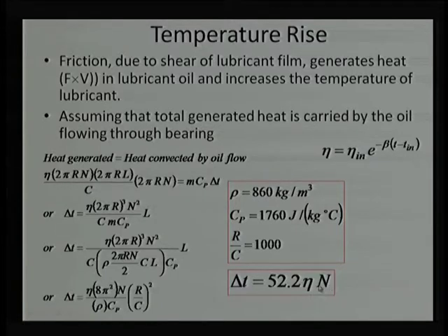Now, we can clearly understand from this relation that if viscosity is increasing, temperature rise is going to increase. That is a very interesting thing. An increase in viscosity is going to increase the temperature rise, and an increase in temperature rise is going to decrease viscosity. So it will be an iterative loop to finally come up with the result.